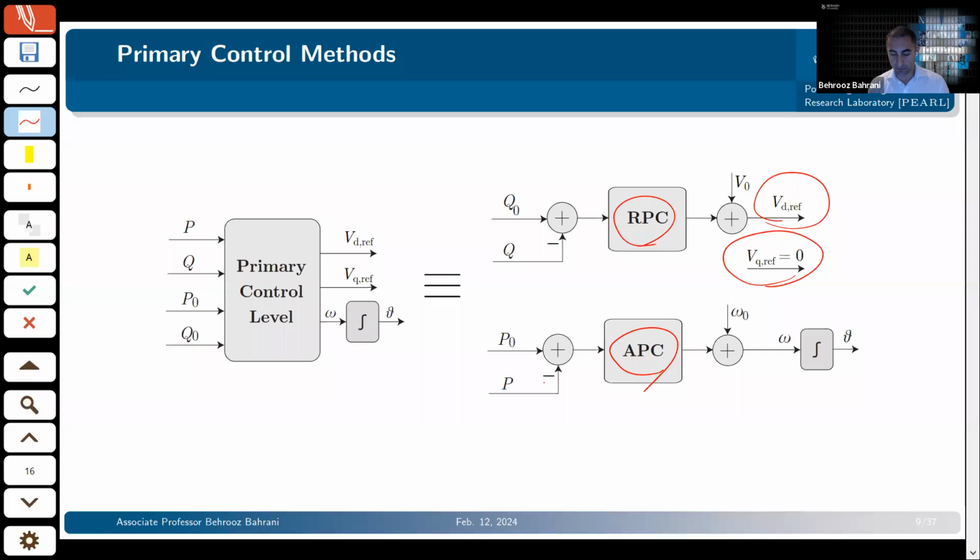And also, you have this proportional or linear relationship sometimes between your real power and your frequency, and you can get the frequency that you require for your operation. So this is a typical way. Having said that, if you've got a system which is not really inductive, and it is something in between, you've got an X/R ratio of 2, 3, 1, so it means that you're not really decoupled, even though this can work, but it's not perfect.